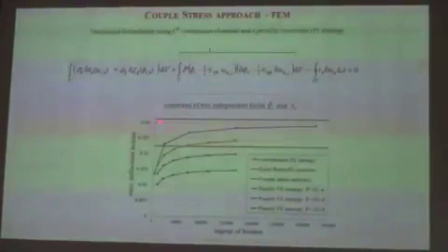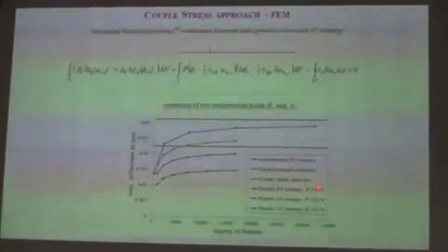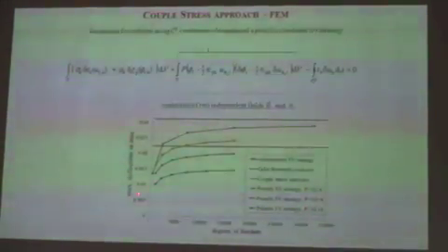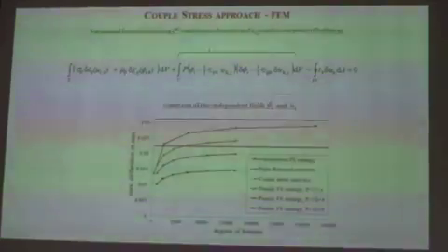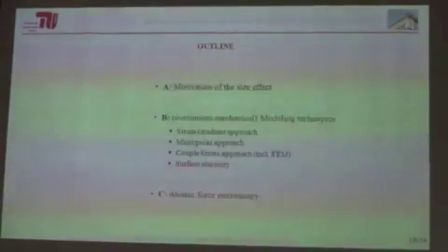And if you do so, again, we have the Euler-Bernoulli beam results, and you have the coupled stress results. The conventional FE strategy now has somehow a bad convergence due to C0 elements and tetrahedral element shape. But if you increase or set P to certain values, you can see how the convergence is dependent on this value, and you can find a good P value to have a good convergence to the coupled stress model and to do further things with it.